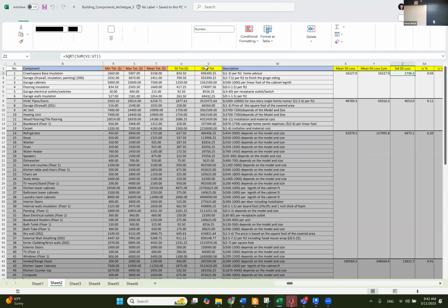So you have this like 1,600 and the total replacement cost of the building 500,000. So you divide the 1,600, the 16,000 over the 1,000,000, and then you will find out that it is 0.04, it's 4%. And damage state 2 is 11%, damage state 3, 20%. And the sum of all of these should make 100% of the replacement cost of the building. Do you guys got that?